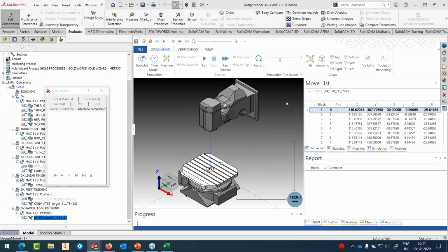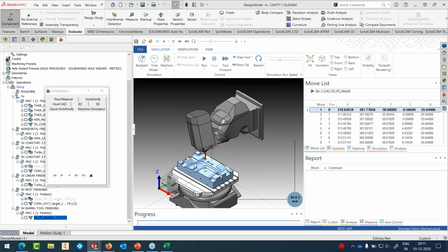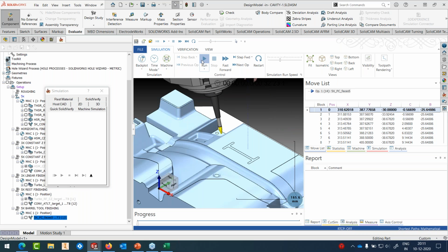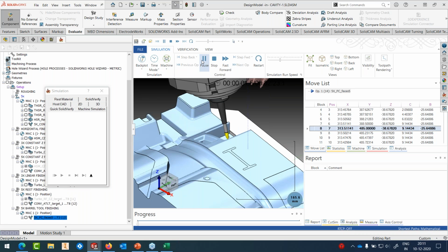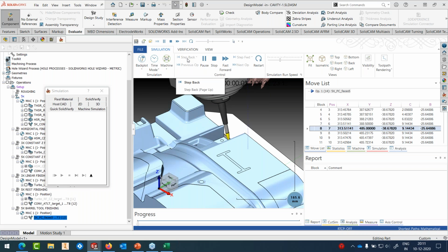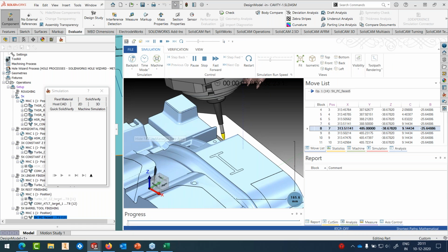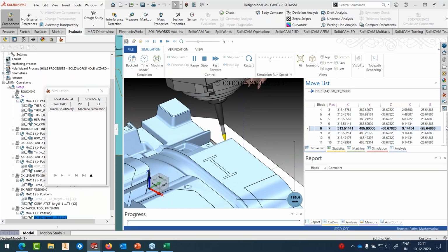The same thing is possible when you would like to machine a surface below a flat area, but it's too deep. You can use what we call a lens form tool to machine those areas. And this is how it will cut the area. Of course, I know that when this is transmitted over the internet, it won't look like a continuous motion, but this is how the machining happens. I'll just go down here.